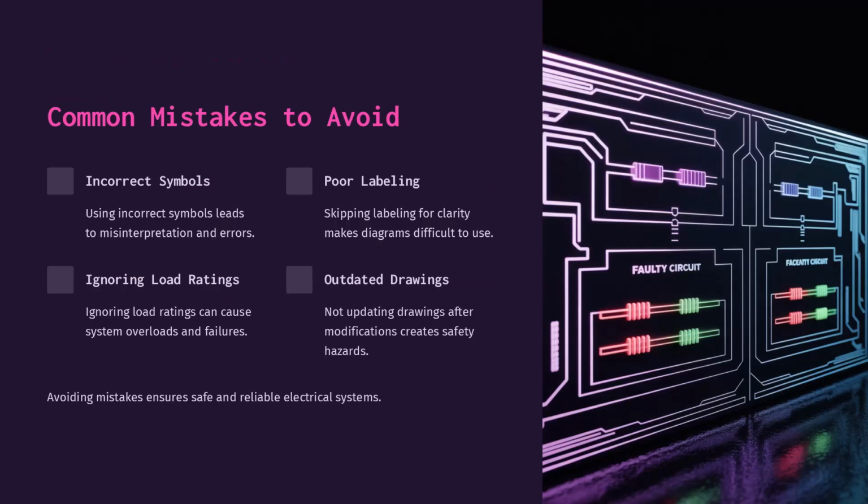Common mistakes to avoid. Let's identify common mistakes to avoid with SLDs. Using incorrect symbols leads to misinterpretation. Ignoring load ratings risks overloading circuits. Poor labeling creates confusion for technicians. Outdated diagrams increase hazards because they no longer match the system.